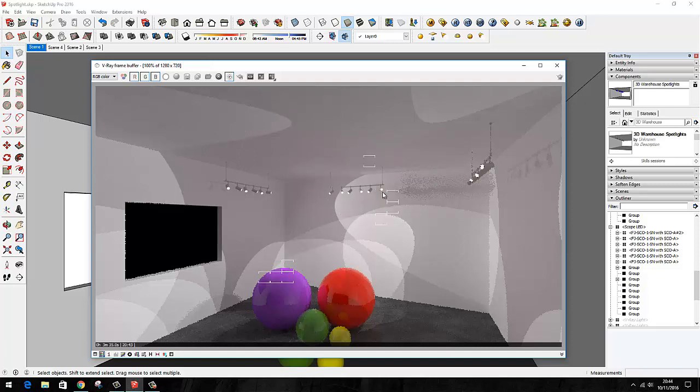Okay, so the light settings aren't set to that higher standard. But what I'll do at the end of this is crank everything up and do a render to see how much difference it makes if we have high quality passes and light bounces and smooth shadows. So the subdivisions will be up to about 32, and I'll set my lighting settings to a high standard. But this is the effect I'm getting.